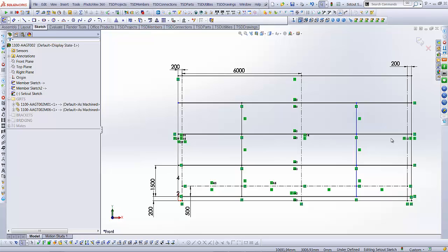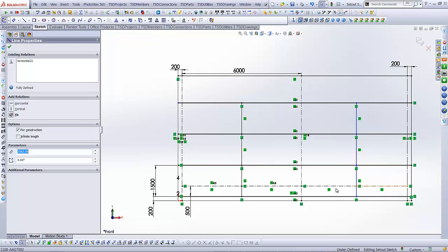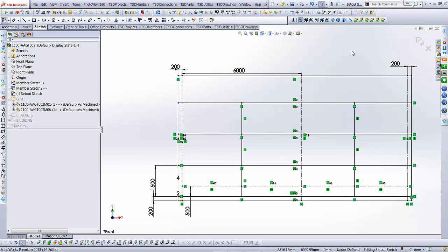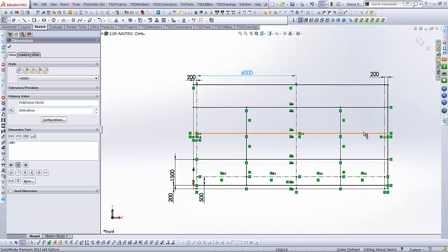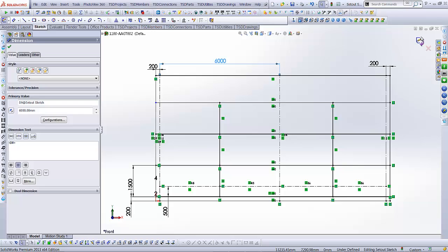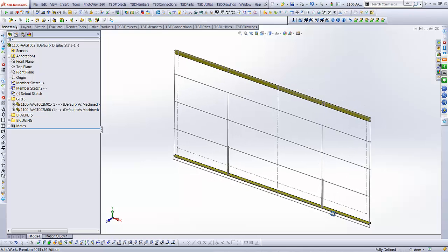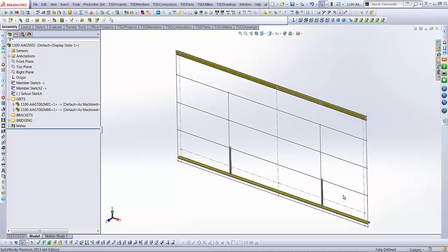The reason that I say lock your dimensions in place is because when you go to insert this, it's going to grow and shrink and it can go all over the place. So the best thing to do is lock it in place. So it's really important that your driving sketches are locked. Okay, so now I've got myself a driving sketch that I can fiddle with, and you'll also notice that because of the changes that have occurred, the girt has updated its length and the bridging has moved across because they're attached to those sketches. You'll notice that in my sketch manipulation processes I try to not delete any sketches if possible, and I'll reuse bits and pieces of components, so that's a quick fix just out of habit.